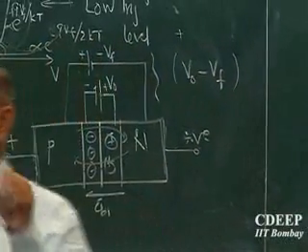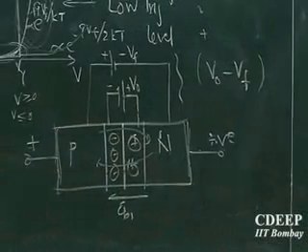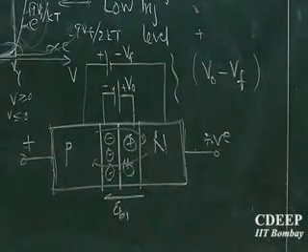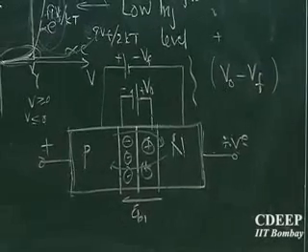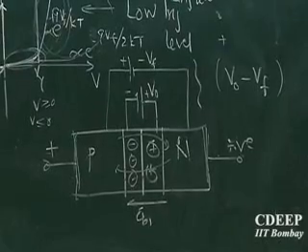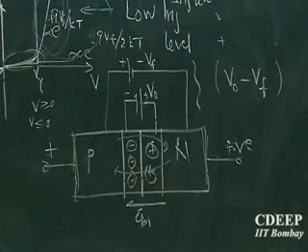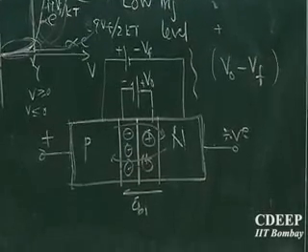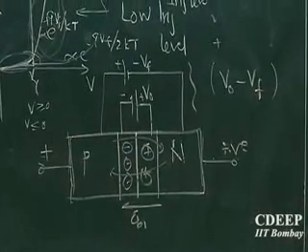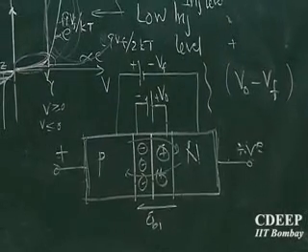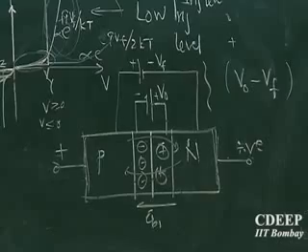As soon as holes move from the P to N region, on the N side, let's say the assumption is low injection as I said, the amount of carriers which the N side receives are much smaller than the N concentration here. What does this essentially mean? Holes are still in minority in the N region. Same way, electrons reaching the P region are still in minority compared to the holes in the P region.